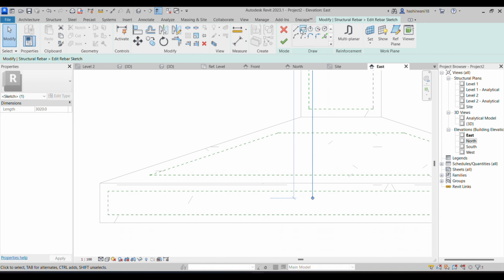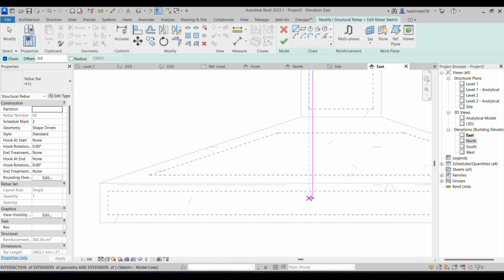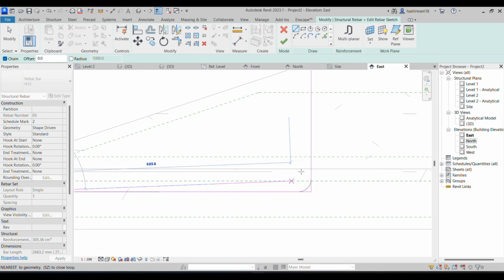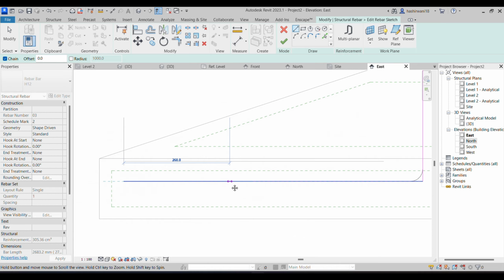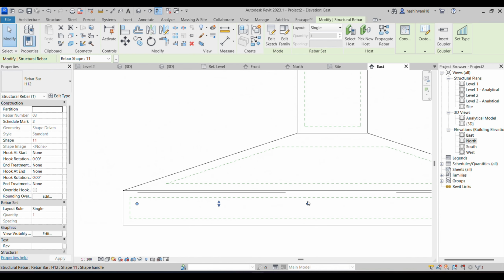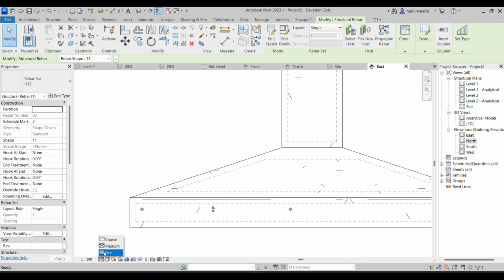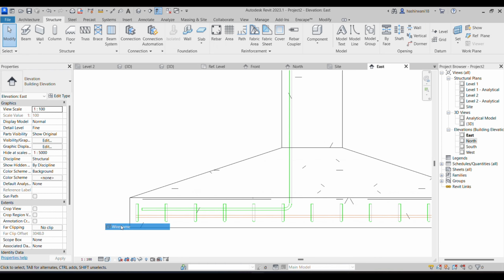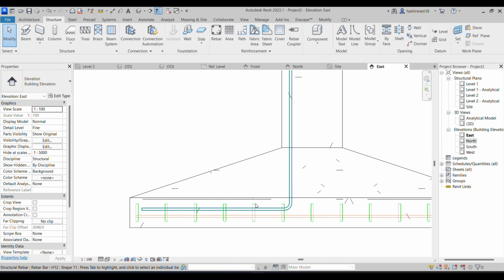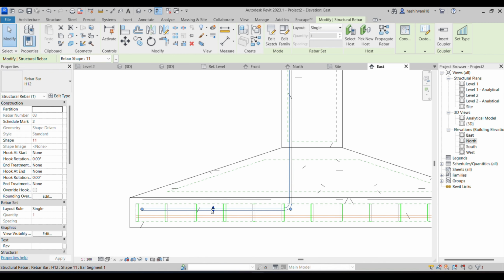And then what I'm going to be doing is, I'll select this align option here. I'll select this, and then I'll just move it across. Can you see it doesn't give a 90-degree angle because your Rebars can't move at 90 degrees. I'll select tick here, and I'll just go to fine here, and I'll go to wireframe here. Can you see this sort of Rebar has been created in this orientation? I'll select this one. I can move it up or down. I'll also be able to move it from here. Can you see I can move it anywhere I want.